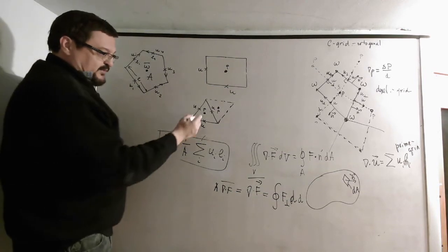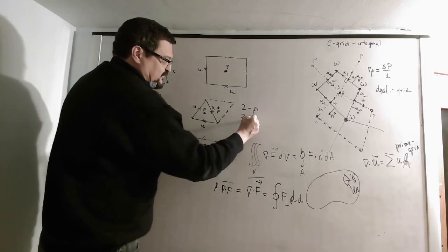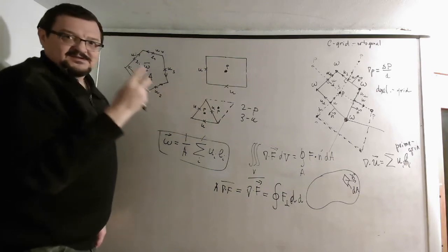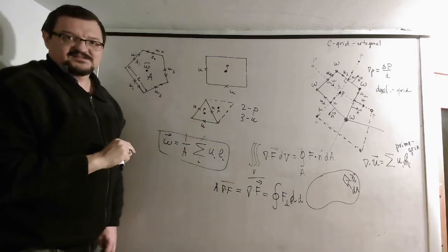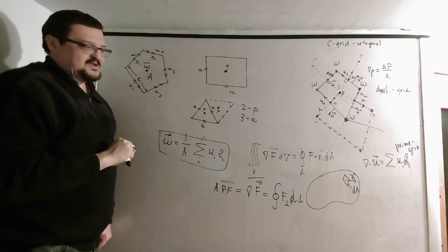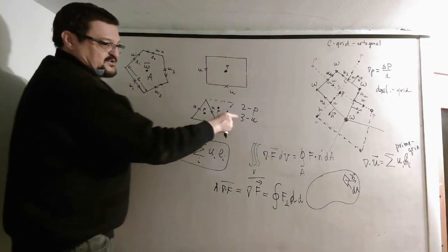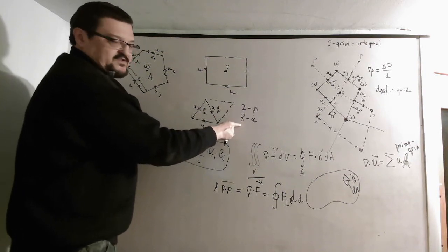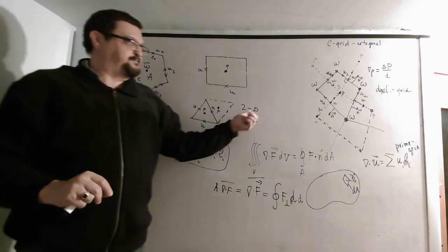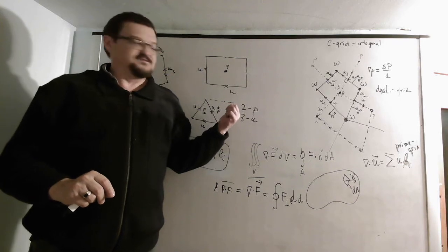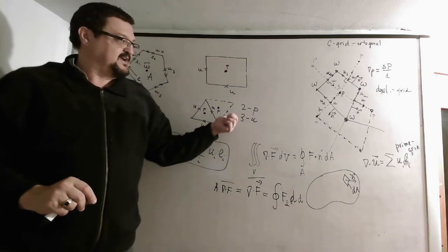Okay, so now what do we have? We have two p's and 1, 2, 3 u's. But we need at least twice as many u's, velocities, as scalars, pressure. So in that case we underrepresent velocities, because for two p's it should be four u's, not three. So now the degrees of freedom for pressure, for scalars, are overestimated relative to the number of velocities needed.